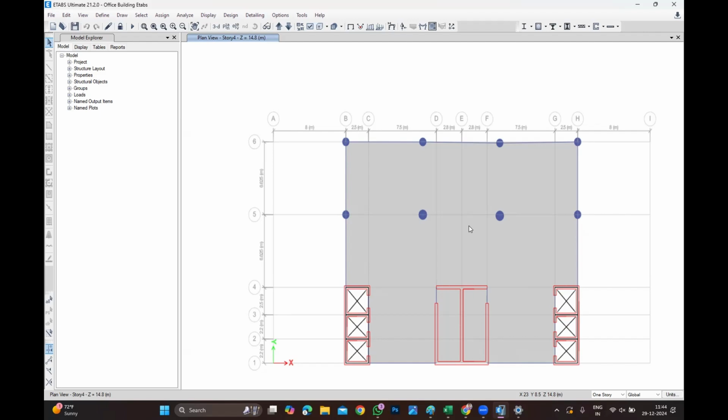If you do a shear wall, you need to see what is the mass of the shear wall and what is the stiffness of the shear wall. Having one staircase, you cannot say that you have a dual system. One staircase, even with a huge footprint, or two staircases, is not going to take 80% of the forces. It's columns plus shear wall: frame elements plus shear wall system.